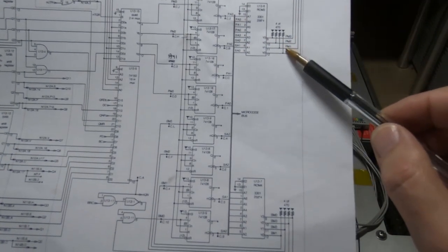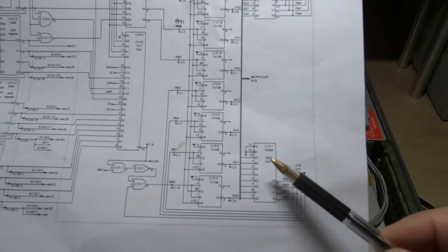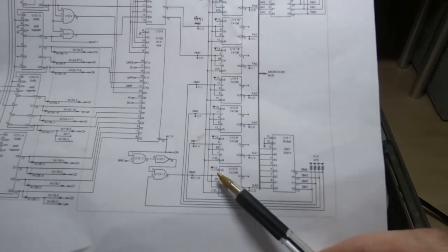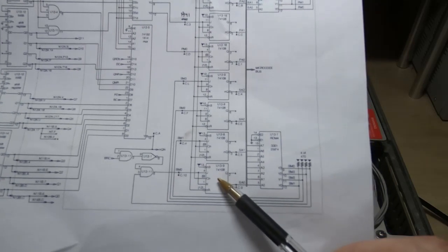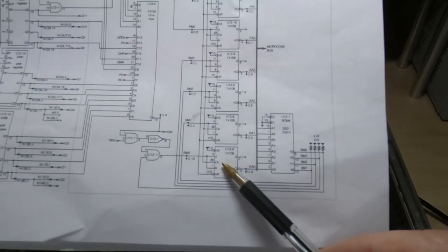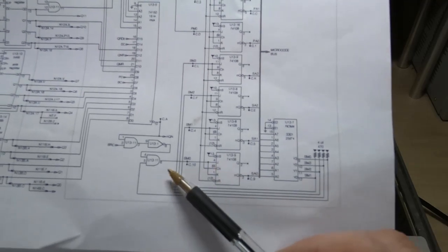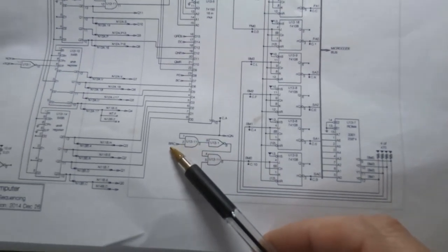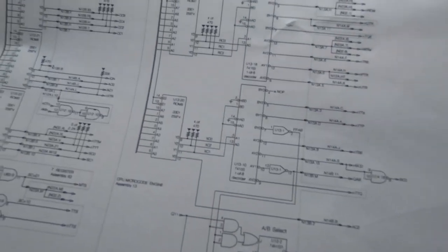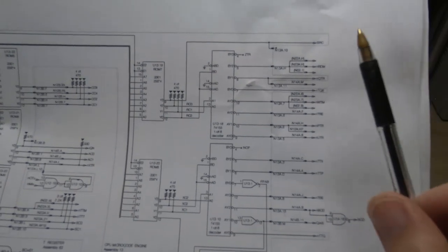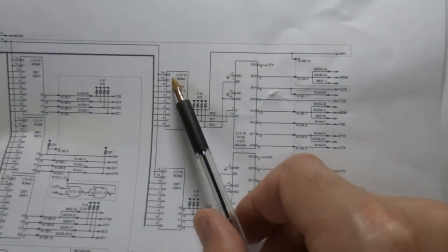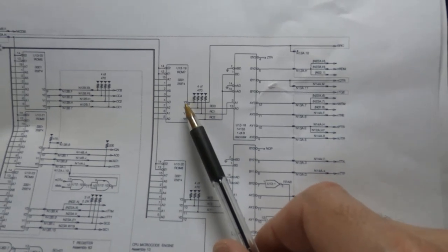The data coming out of the ROMs was correct. However, the following address, that's the next address, was incorrect. And it appeared that bit 0 was a 1 when it should have been a 0. And that turned out to be because the BRC signal is stuck high. Now the BRC signal is derived directly from one of the ROMs on this card. So looking at this ROM appeared to be the next step.